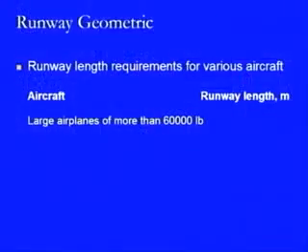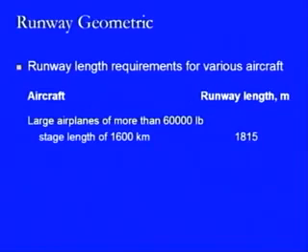Then there is one more case here where we talk about the large airplanes where the weight is more than 60,000 pounds, and in this case it is dependent on the stage length required. If it is 1600 kilometers, then the length of the runway strip is 1815 meters.